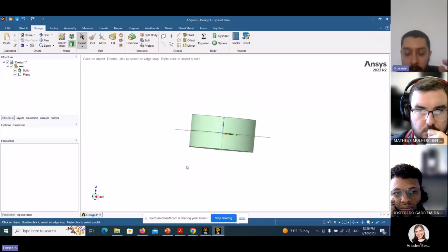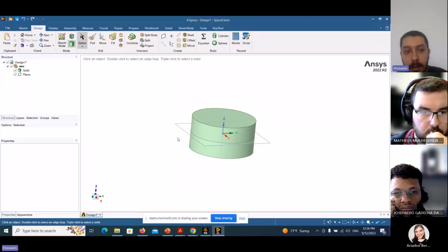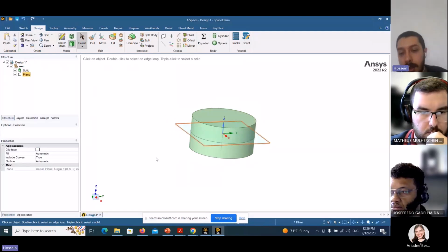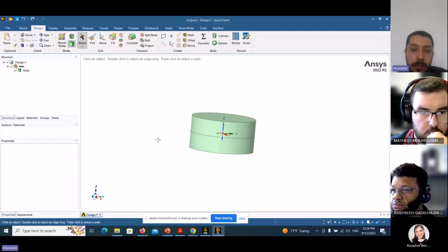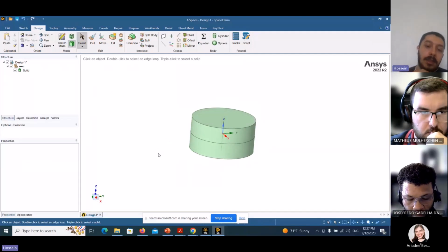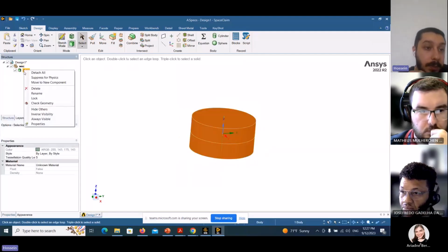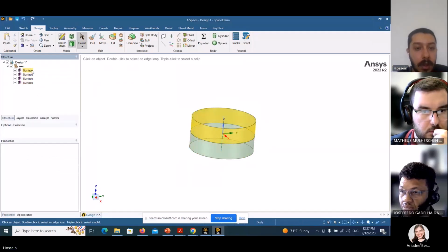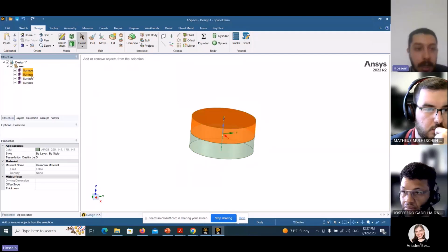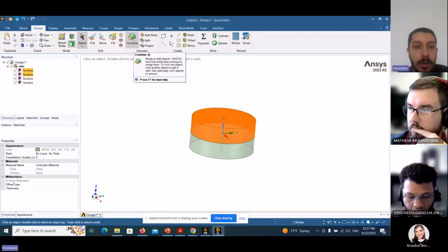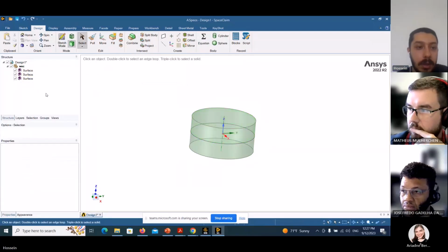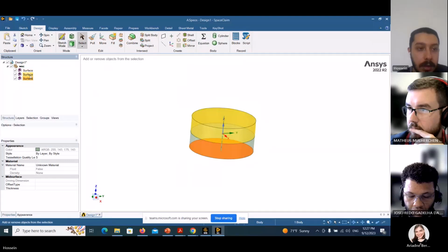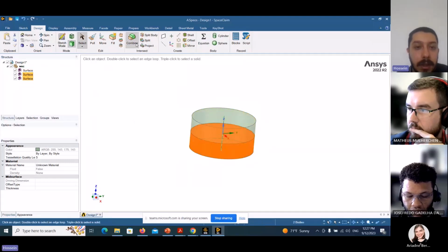As you know, the parts underwater is a diffracted part, and above the water is non-diffracted part. And you can delete the surface, and your structure is separated on the water line. And after that, you can detach this part and make the above part combined and the diffracted part.